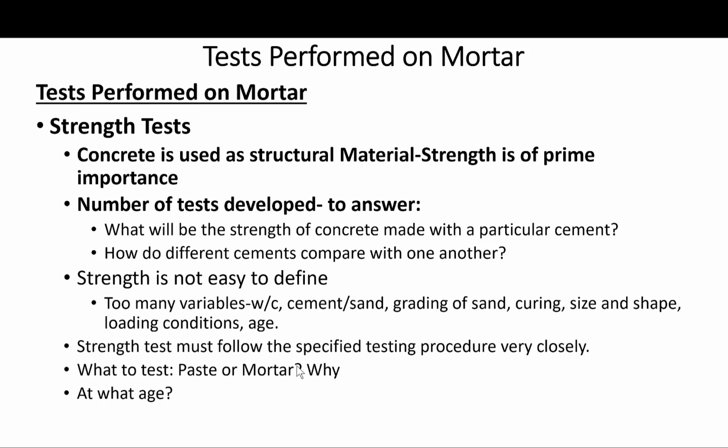Although it would appear to be most logical to carry it out on the neat paste, since the use of sand introduces a number of extra variables, nonetheless, such tests are rarely used today. The problem with neat paste is that it's difficult to handle and test, so more variability is introduced into the result.